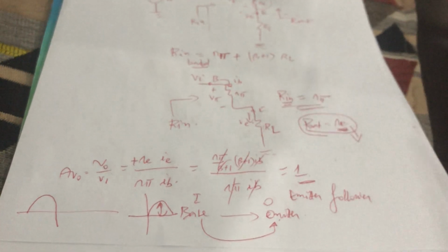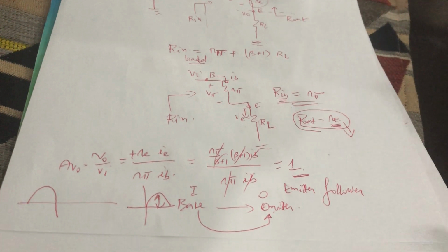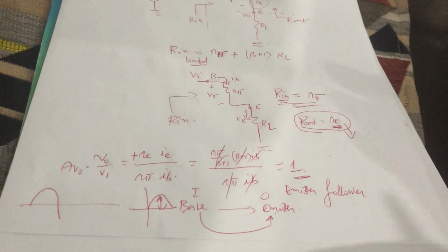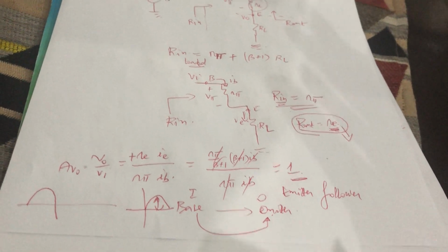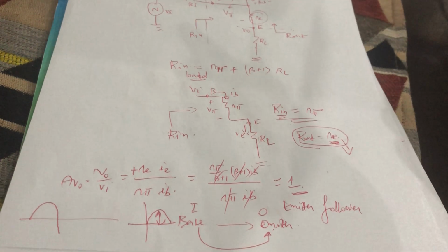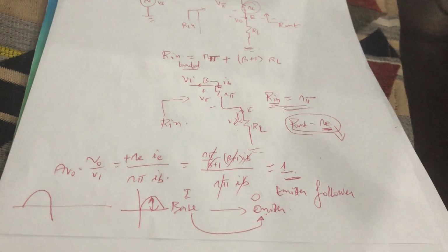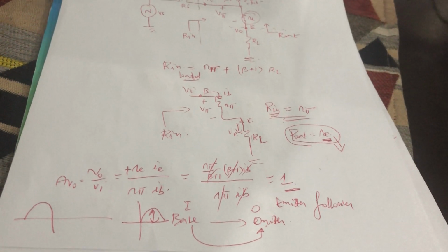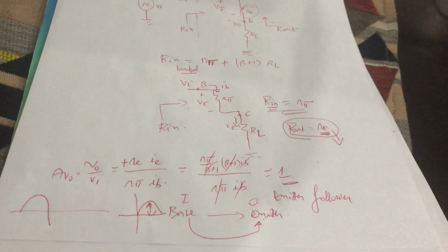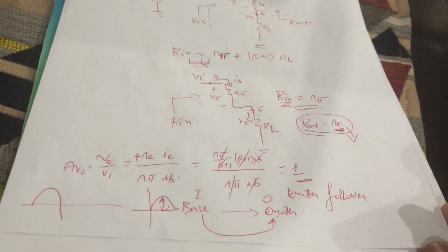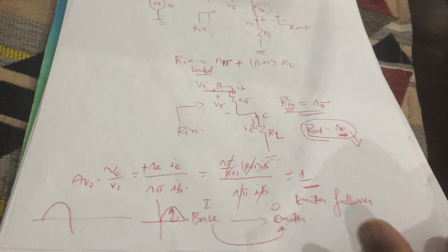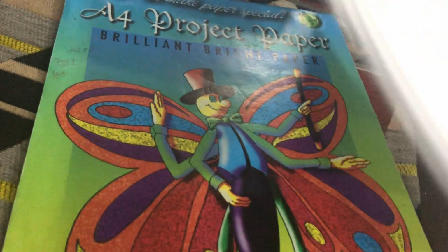That's why, as different modes are being cascaded together to form a good amplifier design, I mean more or less ideal, you normally put the common collector mode at the end in order to tap into its very low output impedance. You're not really after gain out of it, because it has got no gain. It has got a gain of 1 when unloaded, as we proved just now.